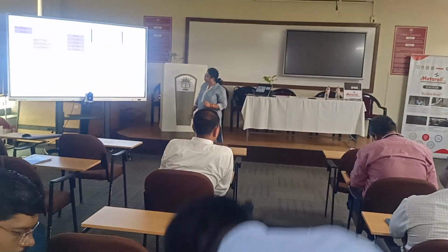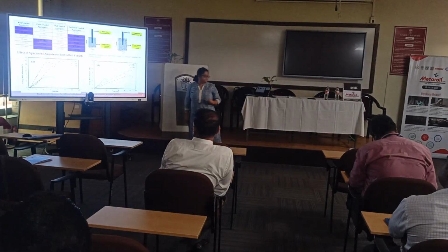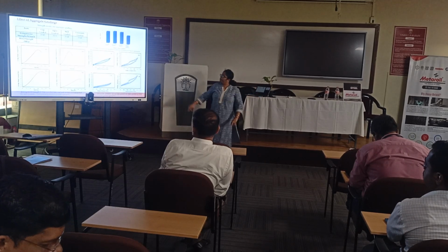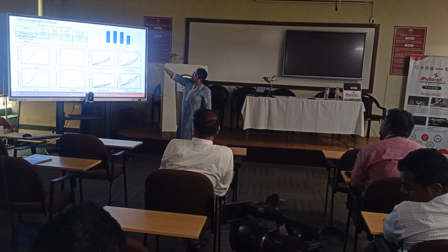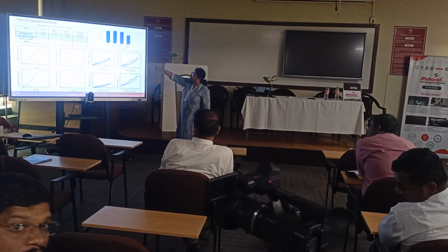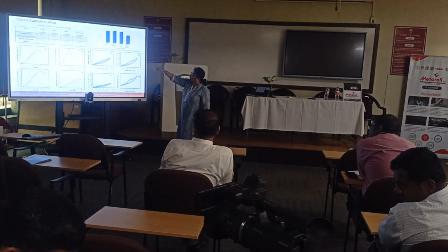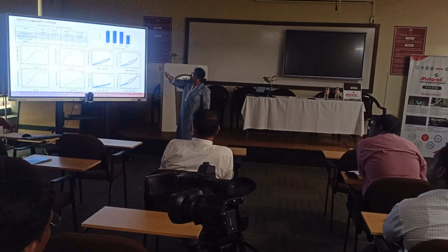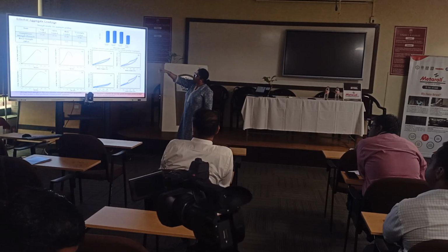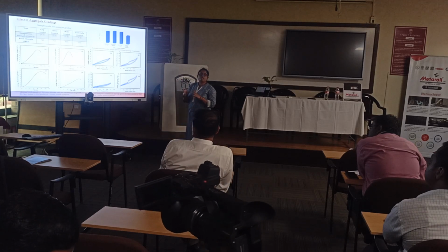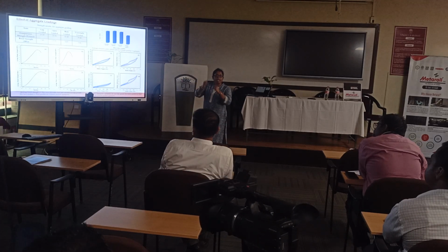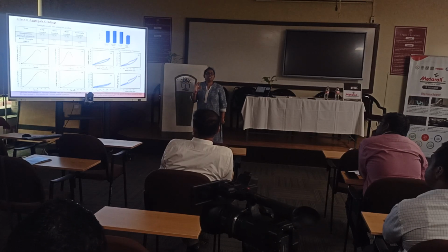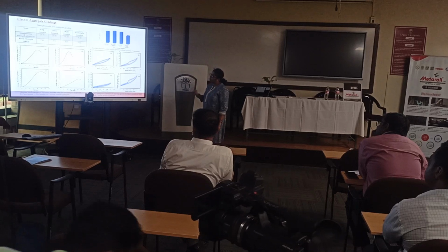If you see, this is not the one. Maybe I'll show you this. The well graded has higher strength, the total strength bearing capacity as well as the bond strength compared to the others. The least is for the single size variation, that is open graded, 3.86, for the open graded, gap graded and well graded. Because of the confinement of the aggregates by being compacted, there is hardly any change in bond strength. So the size variation in overall bond strength is very minimal, what I found.